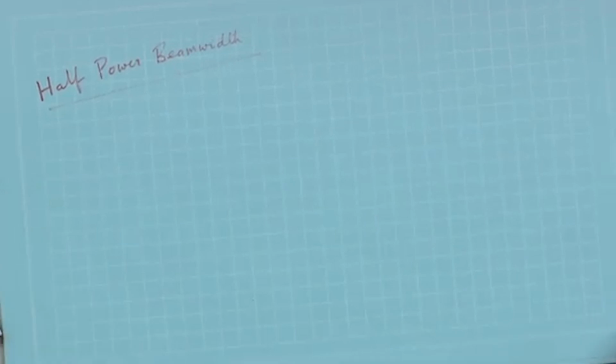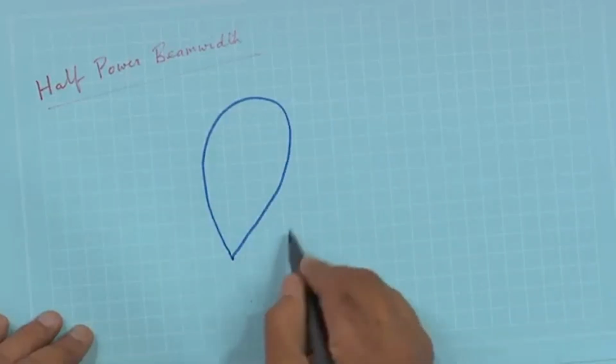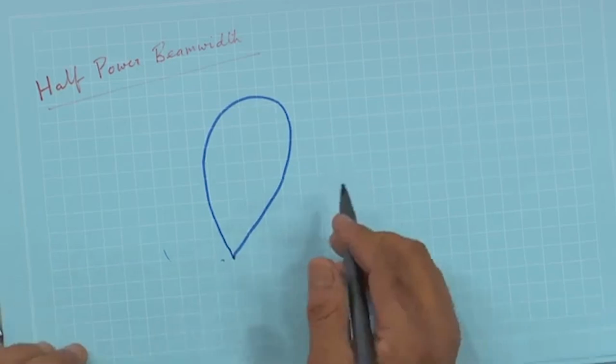Now, you see this also, because generally we have seen in the radiation pattern of an antenna that there is a main beam generally associated with each antenna. So, most of the power is concentrated into the main beam. That is why how wide that beam is, is a useful criterion. If I have a very narrow beam, but I have sufficient power, then that is good, that means the antenna is very directive. So, suppose this is the main beam; obviously there are side beams, I am not drawing them.